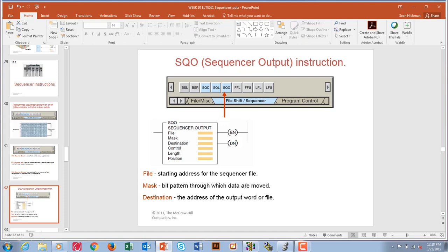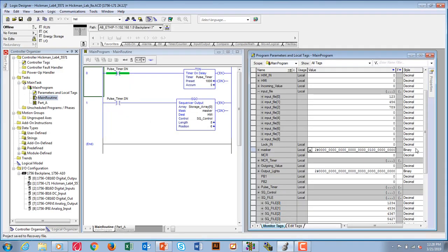We already did the masking. So if you just want everything to come through straight away, then your mask is just going to be 111111, which is FFFF. So you wanted to make your mask -1. If I looked at my mask as a hexadecimal, that made everything FFFs, which if I looked at it in binary is 1111s. So if you make your mask like that, then the word and the data comes through perfectly without any changes. Versus if you make your mask 0, things get modified.